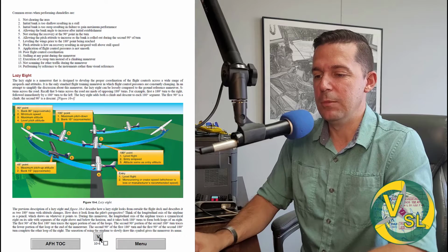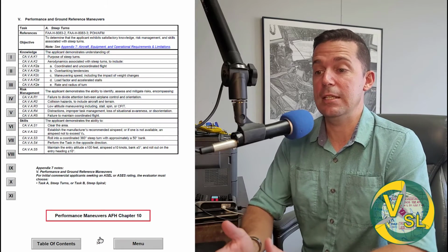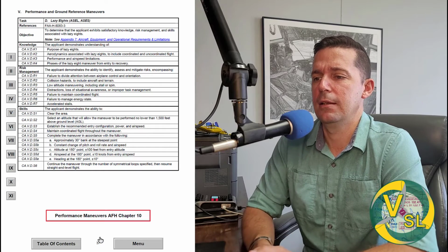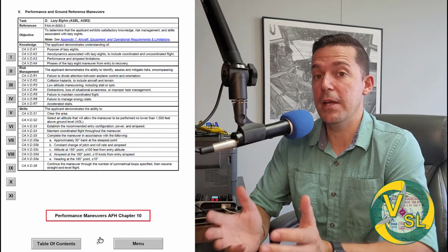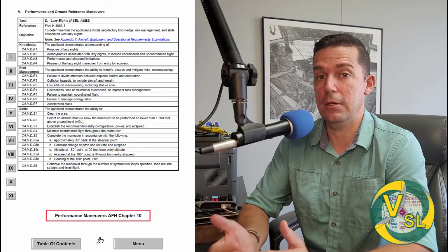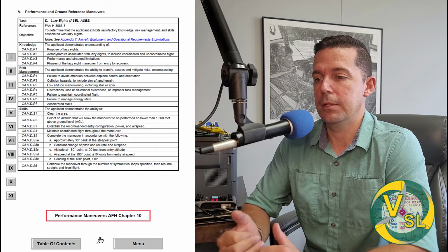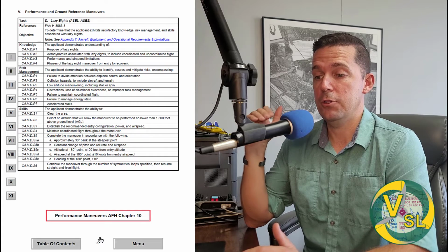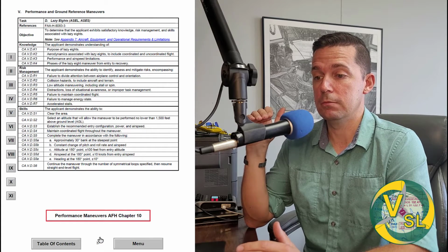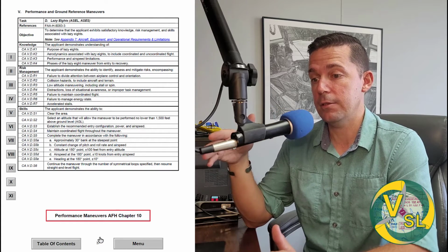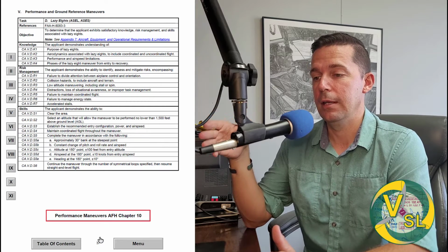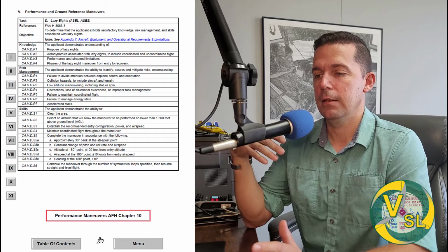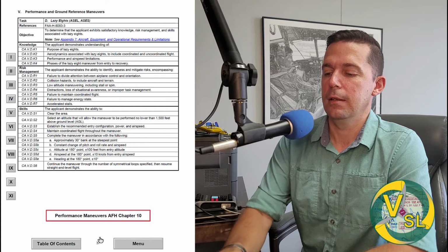It's one of my favorite maneuvers to do or to teach, because I think the lazy 8s really are the best maneuver for you to master energy management, because really you shouldn't be jockeying with power that much or at all. You should be able to do the maneuvers successfully and within these tolerances without ever having to touch the power, and you're managing everything with pitch and bank. It's a very fun maneuver to do, I think.